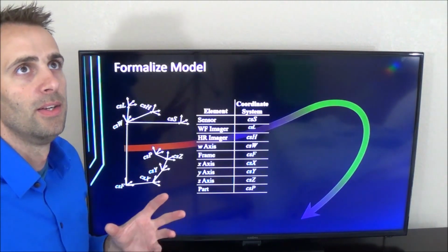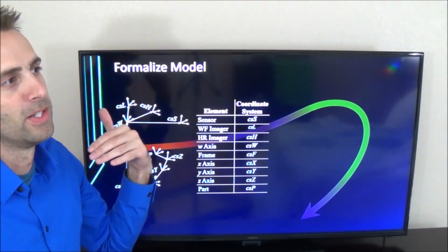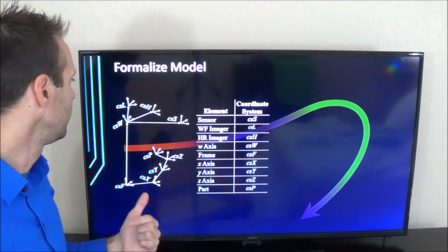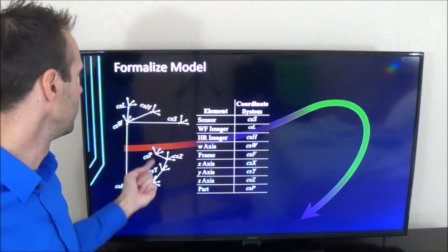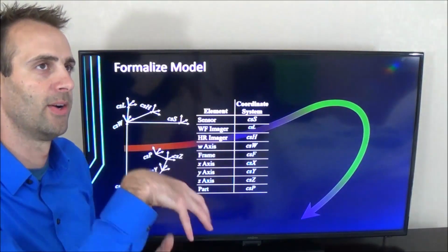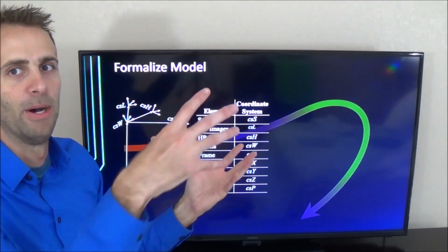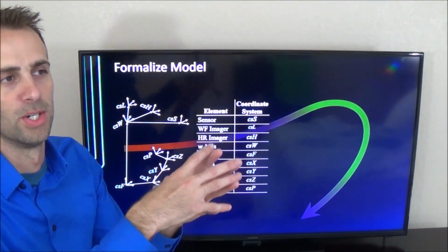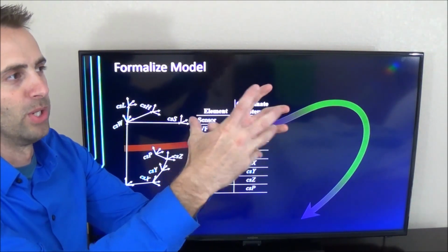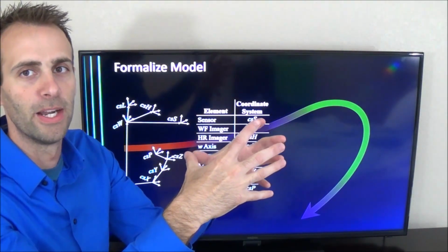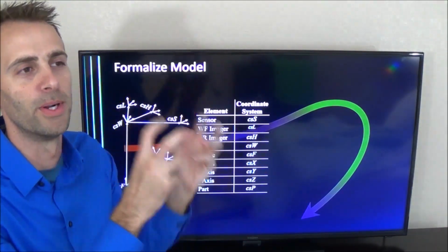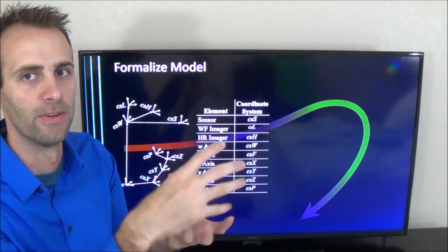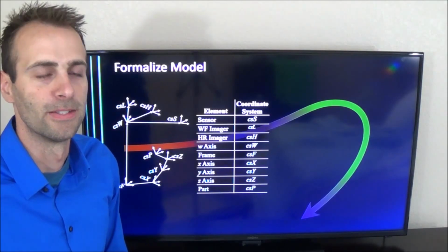So what I like to do just up front is think about, okay, if it's a measuring machine, then I'm going to be going from sensor coordinates to part coordinates, because that's how I map this out. We'll say it generates some point cloud in the sensor itself, and then I want to transform that into part coordinates to find out what I'm measuring given all the different configurations of the machine.